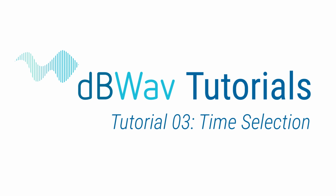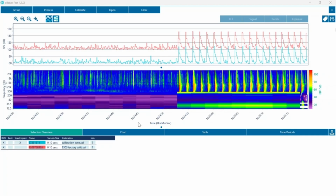In this tutorial, we are going to learn how to make a time selection. First, navigate to a region of the time trace or spectrogram plots that you would like to study in more detail. To make a time selection, left-click and drag over the region of either the time trace or spectrogram plots. The whole of the visible plot can also be selected using Ctrl-A.